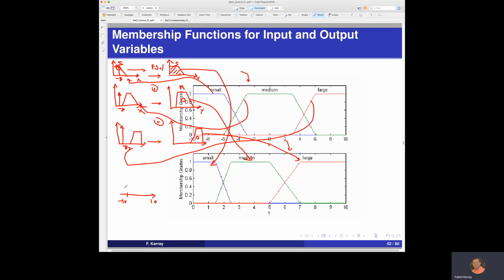Okay, so for the value of -8, for this particular instance, we have only this membership function and this membership function. If we express it here, it's going to be the aggregate. The aggregate membership function for this -8, we have to extract and find its center of area. The center of area happens to be this particular value of the output, which is going to be the control effort for the system when it is subjected to an input value of -8.